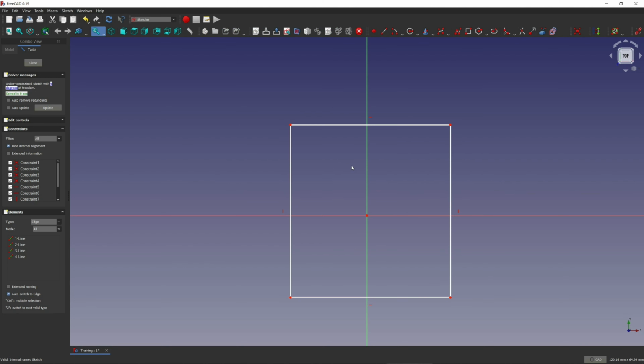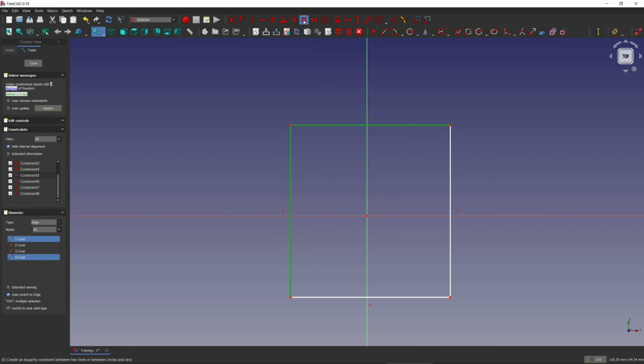Basically, we just took a lot of shortcuts and we created a 3D object out of the 2D sketch that wasn't properly constrained. So now we're going back and we're actually going to set up the proper constraints and follow the correct practices. So the constraints, as I understood them when you were explaining, are the degrees of freedom of movement that this particular two-dimensional object has. To make it exact and give it the exact dimensions that we want, we need to put in place constraints, and this prevents movement where we don't want it. Is that correct? Yes, that is correct.